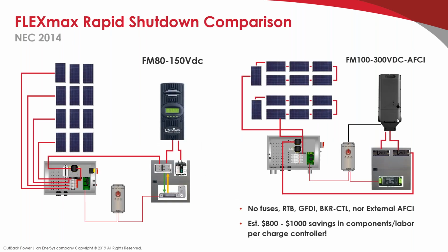And some quick review of the wiring diagrams of previous solutions. So 2 contacts inside, you have your circuit board inside, that's for arc fault detection, your arc fault card there. So there's a lot going on here, of course. So we wanted to make sure that going into NEC 2017, we didn't require a large complex combiner box along with module level rapid shutdown, because that would be a pretty high level of obstacles to comply with NEC 2017.